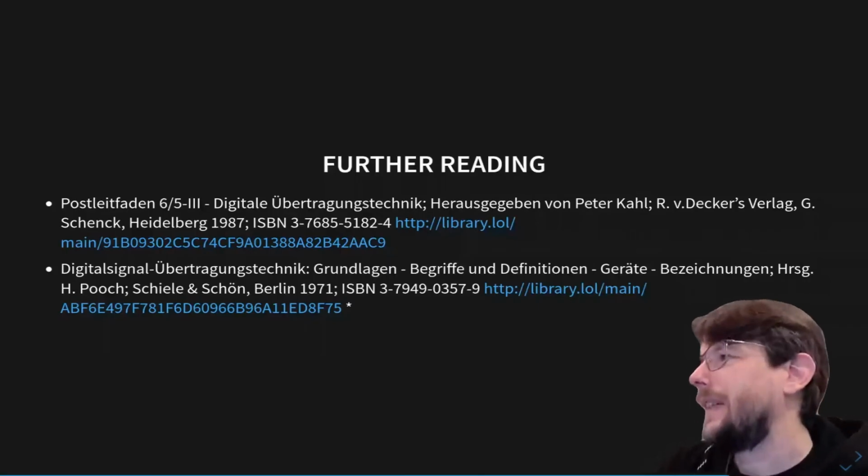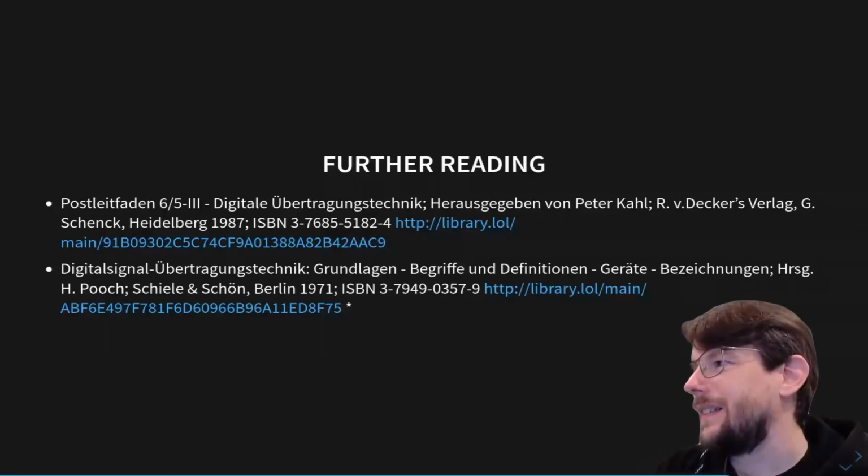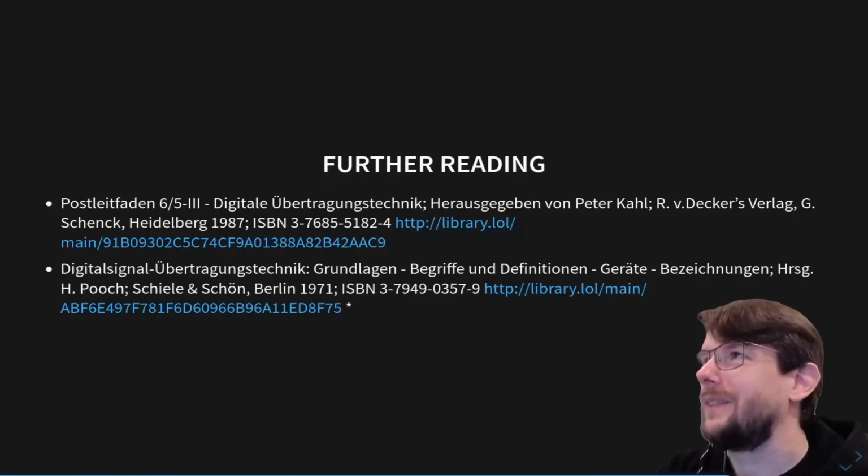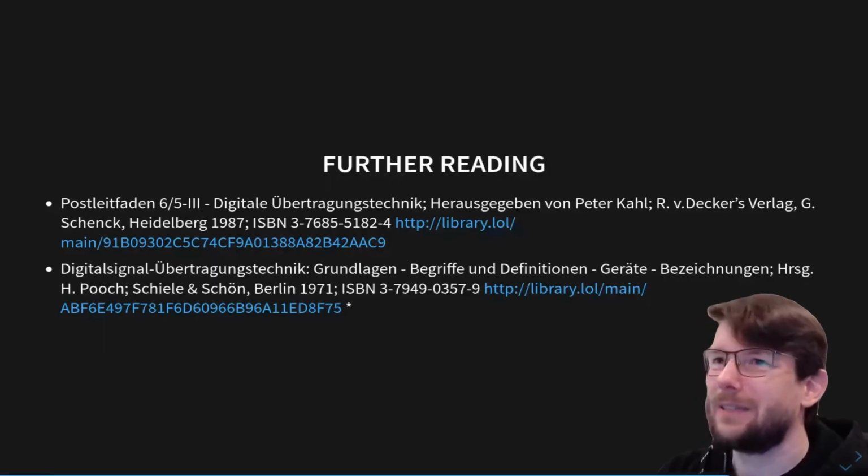Yes, but I don't think we necessarily guarantee that the 31 time slots, the 31 bytes of an E1 frame excluding TS0, are reproduced at exactly the same multi-frame or frame number in the multi-frame at the receiver side.